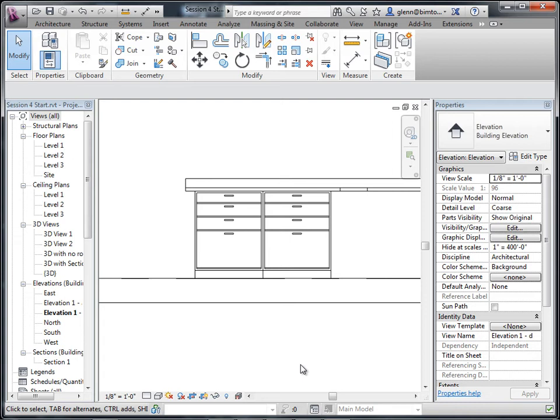Even that whole notion, can you think of this? Floors are really just extrusions. Does that make sense? Because that pink line mode, and then floors are really just extruded elements. So, okay, literally this. You know how to make a hole in a floor. Okay, how would you make a hole in a countertop? It's just as soon as you make an interior loop inside of the exterior loop, it's a hole in the extrusion.